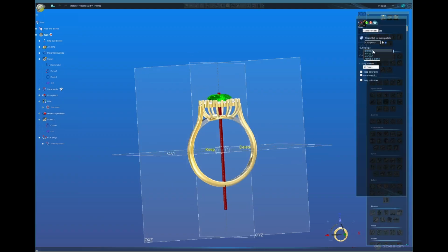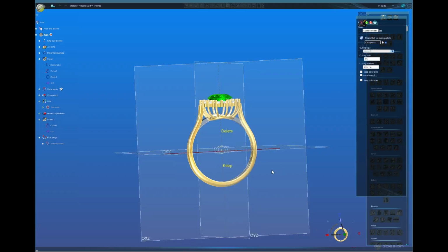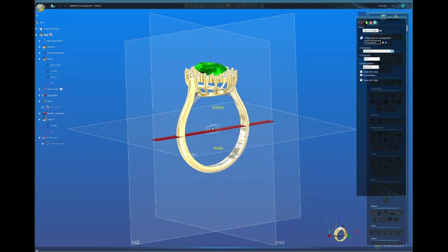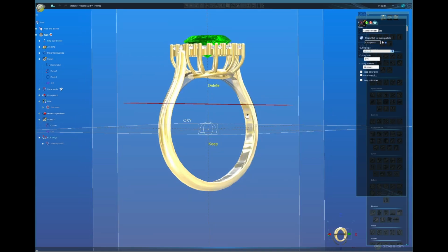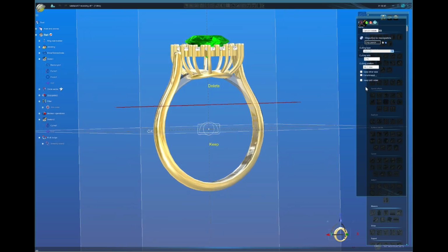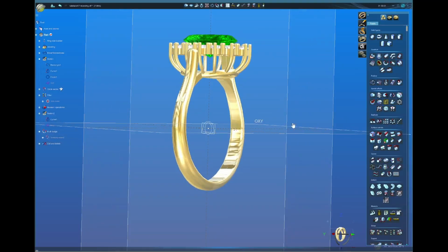We're gonna be cutting on Z, and you can cut up to here because if you see the shadows there, after here we don't need that anymore. So let's cut. You're gonna keep the other side because it's gonna delete this part. We want to delete this part, so keep the other side. We're gonna delete this one now. Click OK, and that's it.